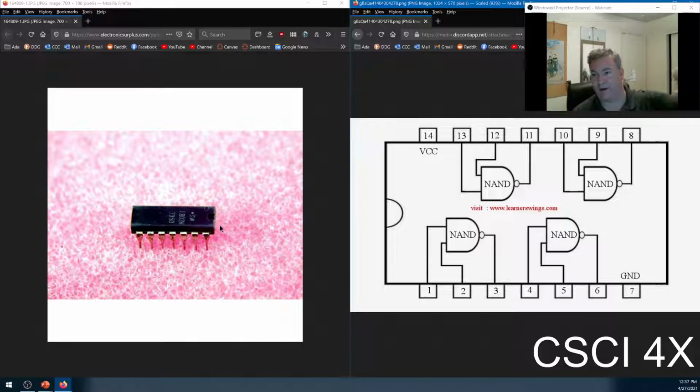And so if you run it through a relay, you can have like a 9-volt battery pack attached to the relay, attached to the motor, attached back to the battery pack, and then your Raspberry Pi just turns the switch on. Hey, it hits a switch over there, turn on, and then the motor spins up because it's powered by the battery pack. Okay, turn off, and that stops. And that is how you typically will do high load things like motors and things like that.